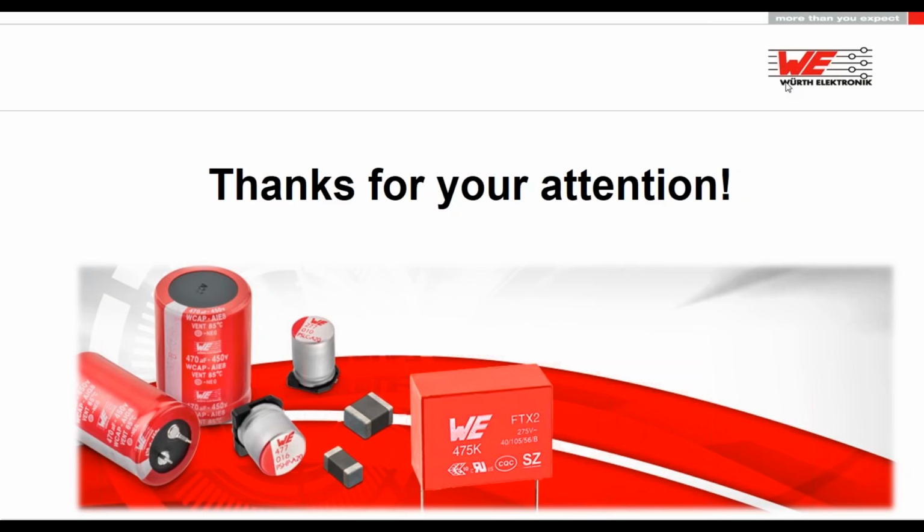So over time you lose electrolyte, and this loss in electrolyte will result in ESR increase, because you lose interconnectivity from cathode to pins, and you also will lose capacitance, because the electrolyte within the E-cap is the cathode itself. And so if you have less electrolyte inside the cap, the capacitance will decrease. So if you see over time that the E-cap decreases in capacitance, this is related to this so-called dry-out behavior.